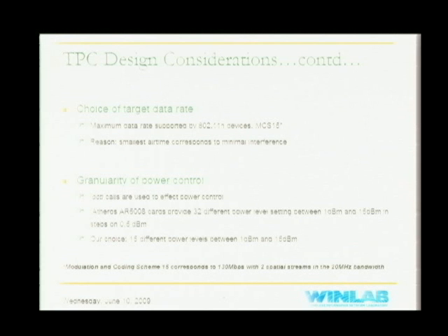So we disagree with the statement that the smallest airtime always corresponds to minimal interference. I think there is a conservation law here, because the total interference power is going to be the same whether you transmit at lower power and longer period versus more power and shorter period. So unless you actually reduce the data being transmitted, there is more or less a conservation of interference.